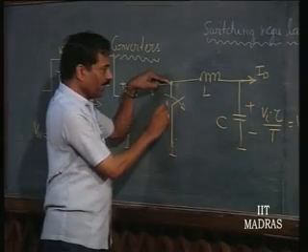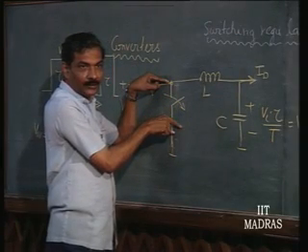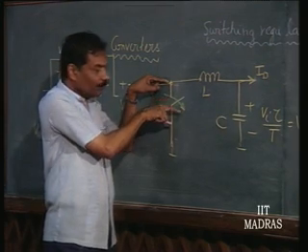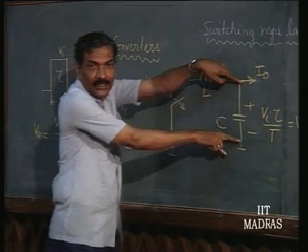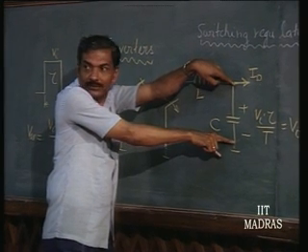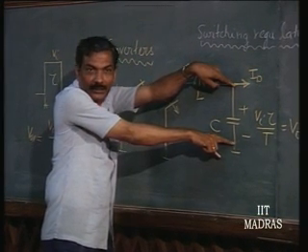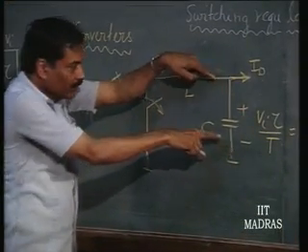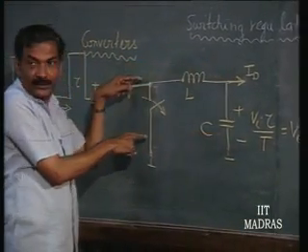It is going to be Vi when the switch is open, 0 when it is closed. So when it is open, this is Vi, and what is the voltage here? At all times it is V equal to V naught. I am going to consider that; it is not correct, that is an approximation, but that is good enough. So this is V naught and this is Vi.